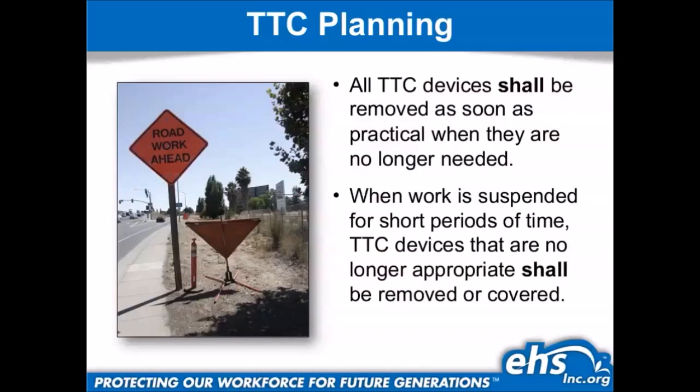sometimes think of your regular commutes around your local cities, right? Sometimes you'll find that people leave their equipment out, like the traffic control signs and the cones, and they'll leave lanes closed. But when you drive past the site, you don't see any hazardous equipment. Say, no heavy equipment like a skid steer. Yeah, if they leave a skid steer on the roadway, then you definitely want to close off the lane. Or if they leave an open trench or something like that, right? But there are places where they leave all their cones, lanes closed, signs out, but there's no work going on and no hazards that are left over at the site. If that's the case, if things don't need to be there, they have to be removed according to the CAMUTCD.